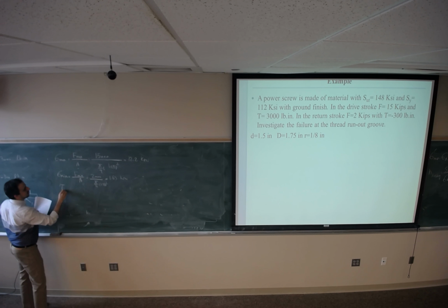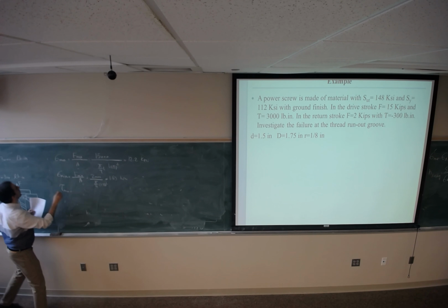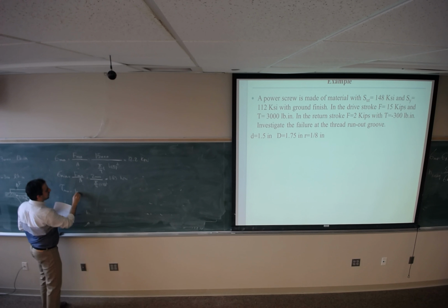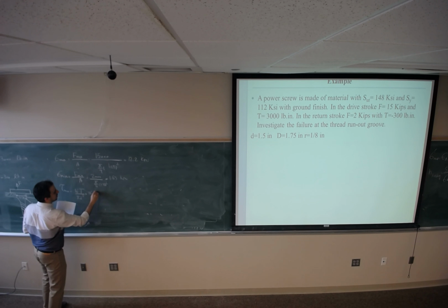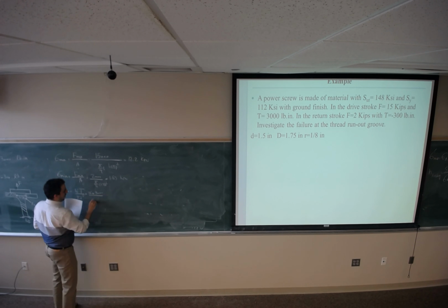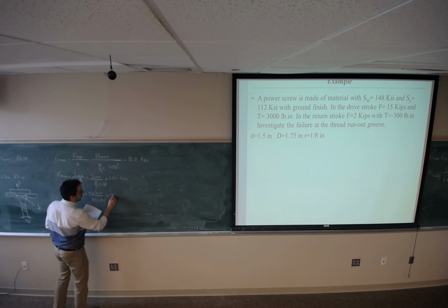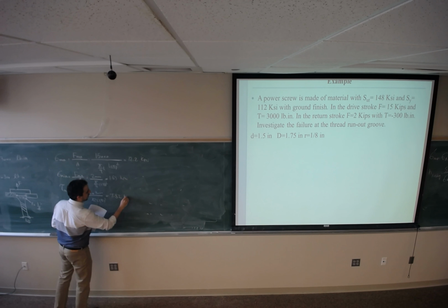Shear stress, for the maximum shear stress when it's moving up, is 16 times torque divided by pi d cubed, 16 times 3000, which gives 7.82 kpsi.